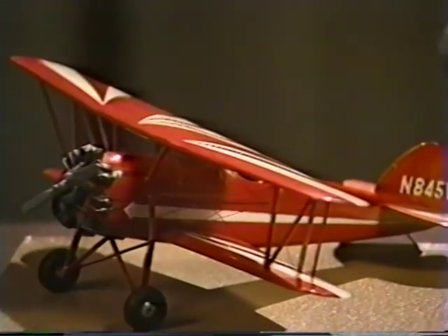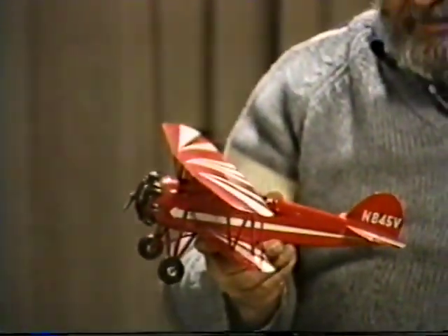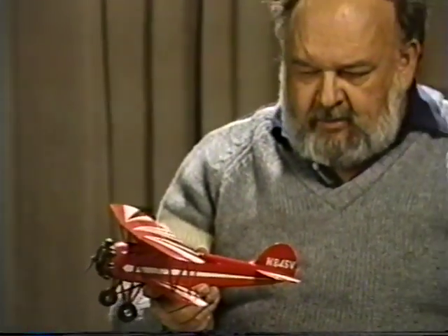If we then take a good look at an airplane and try to understand all of the factors that are presented in here, we have directional stability, which is accomplished by the fin itself. The rudder is the surface that counteracts this directional stability, and again, we can have as much rudder as we would really want. The more we have, the more stable it is, the better a pilot likes it. But you also must have a rudder that's big enough to counteract it.